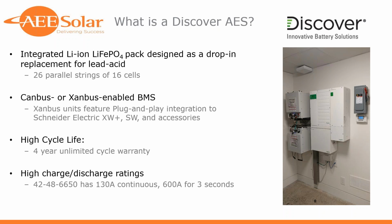So what is a Discover AES? Integrated lithium iron phosphate pack designed as a drop-in replacement. If you're interested in chemistries, we spoke a little bit earlier about nominally around 3.5 volts per cell. The way they get to that is strings of 16 cells to get up to a 48 volt nominal, and then they parallel them to get the current up to be usable with today's equipment.